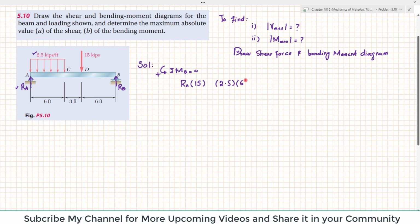This distributed load is converted into a concentrated load acting at the midpoint. So from here it is 3. Clear? The remaining distance will be 3 plus 3 is 6, and 6 more is 12. So the total perpendicular distance is 12 feet. So multiply by 12, and this force is producing counterclockwise moment, so it will be positive.